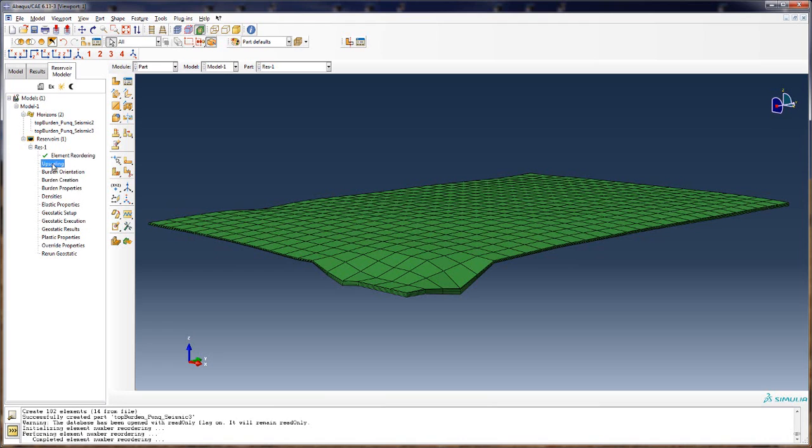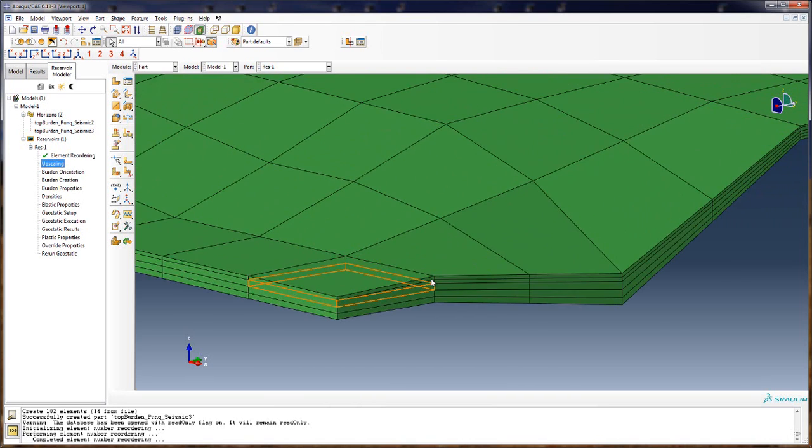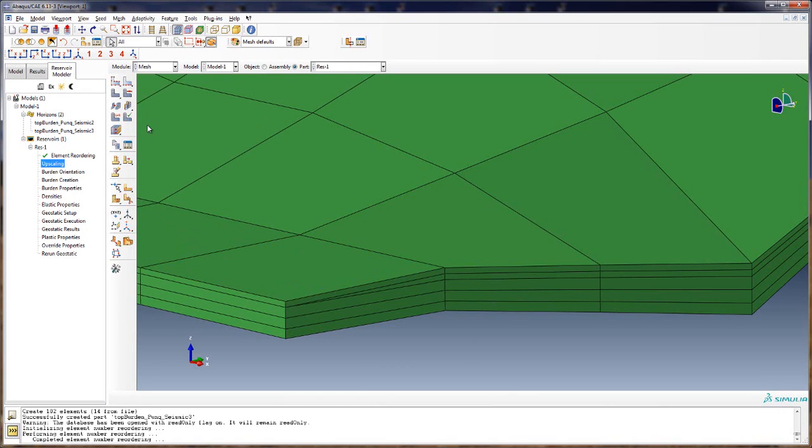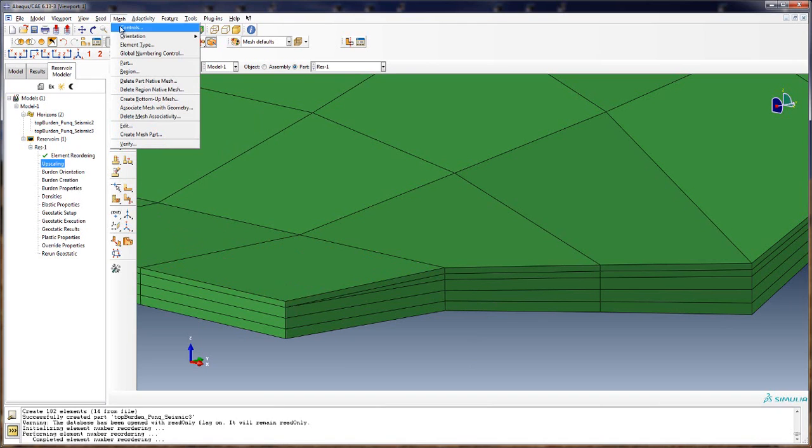All right, so upscaling. That's where we have meshes, for example in this case, where we have this element that collapses down into a wedge. Now there's actually 2 nodes here, so if we were to try to create a burden and extrude this face out, we would have a brick element that's basically collapsed down, and the solvers would fail with an error. So what we have to do is merge those layers into one. This is the only step in this process where we have to jump out of the plugin and work within Abaqus CAE.